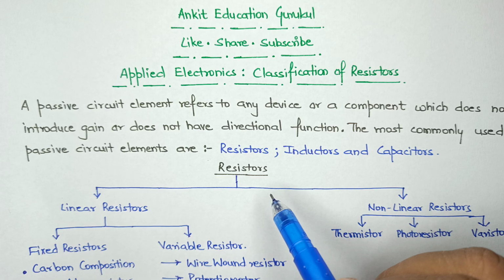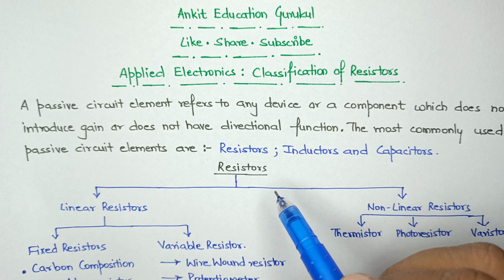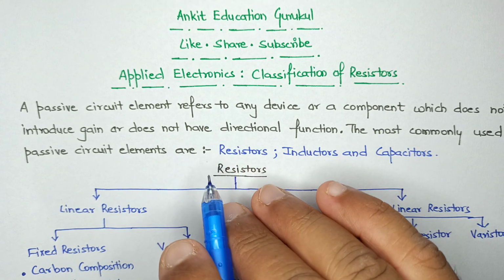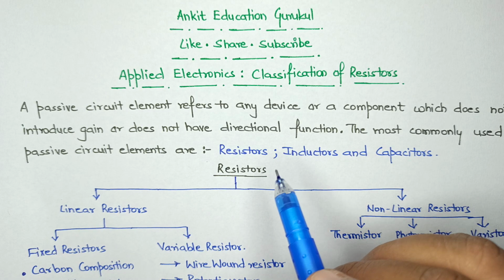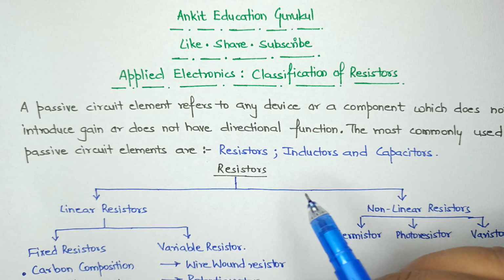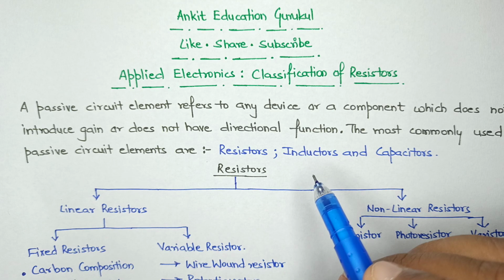The power rating of a resistor is given by the maximum wattage it can dissipate without excessive heating. Since the power rating is proportional to the square of the current, the current must not be higher than its safe value. If the current exceeds the safe value, the resistor will burn out.